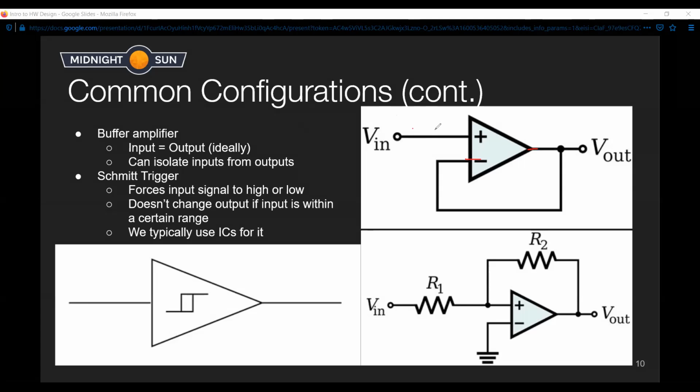So something that I haven't mentioned about op amps is that they actually don't take any current. So the current going in and out is going to be 0. So if you need a signal out on this side, it won't affect the circuit on this side, which is extremely useful for processing signals. This is really commonly used on any input-output stuff. You could see on driver controls, this is used for any analog signals.